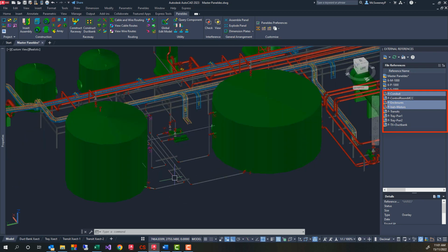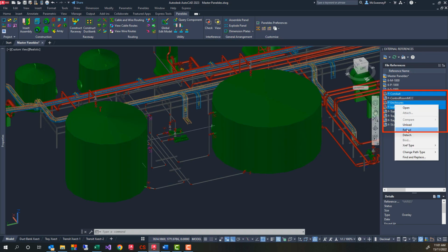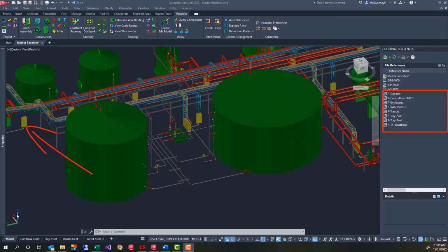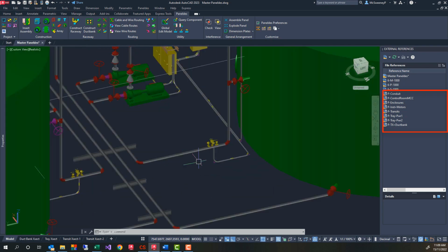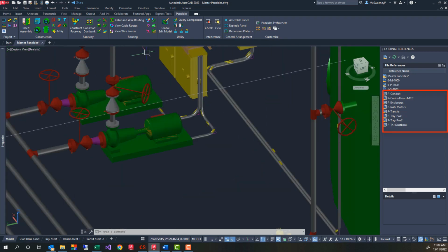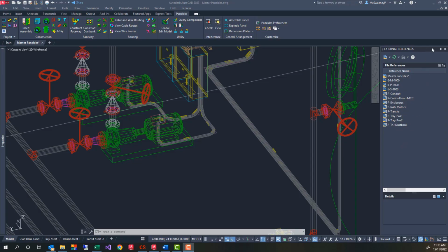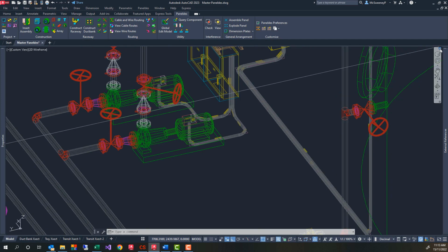In this model, I've subdivided my work by component type, power, and I have also separated out the control room and transformer areas. The larger your model is, the more valuable you will find subdividing it into XREFs. Most electrical objects of the same type in your model will look very similar. The only way to positively identify them is to view their tag name and specification. The components, once loaded, can be identified and interrogated using our query command.